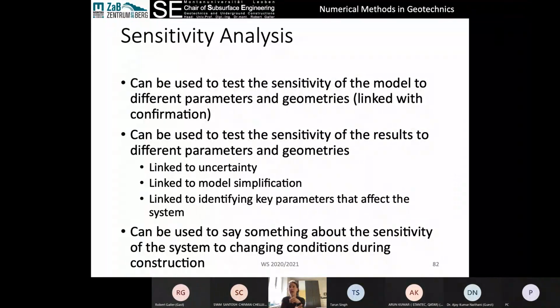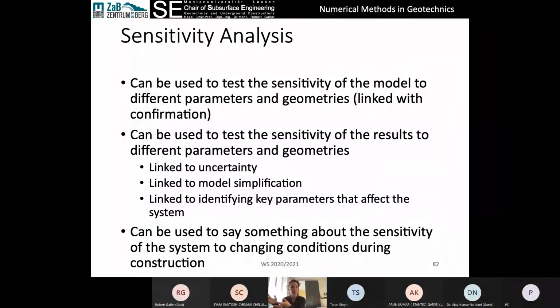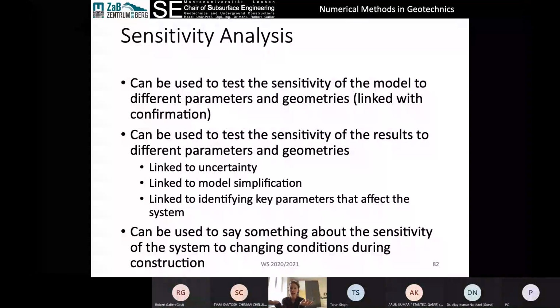We're also trying to say, if we know that we have variability, sometimes we're in a better quality rock mass. So for example, our granite is more weathered and less weathered in certain places, then maybe we have an upper bound condition with the unweathered granite and a lower bound condition with the weathered granite. And then we would do a sensitivity analysis. How much does that affect our deformations? How much does that affect the loads on our liner? What do we need to do for our sequencing? Do we need to do a split heading, for example?